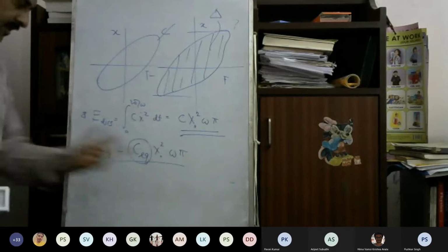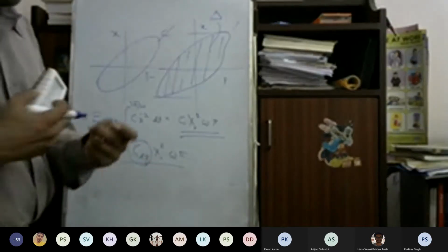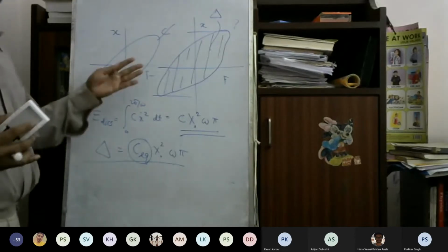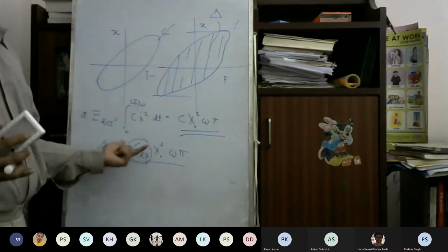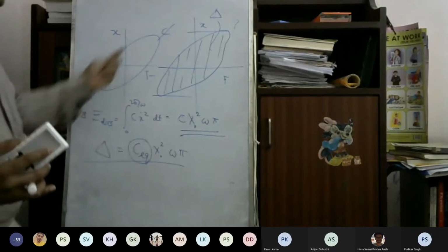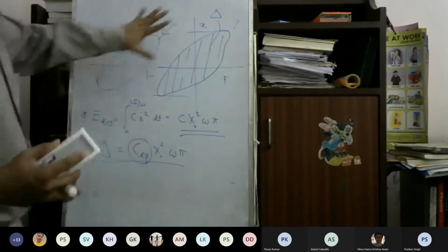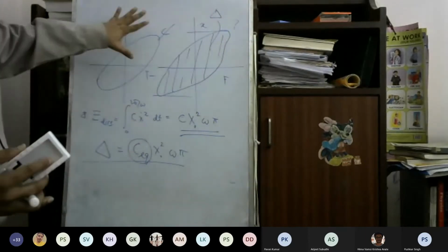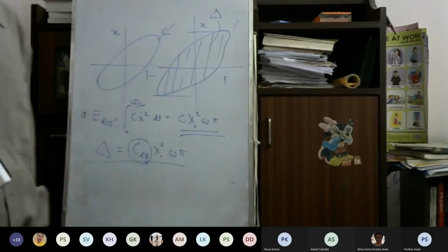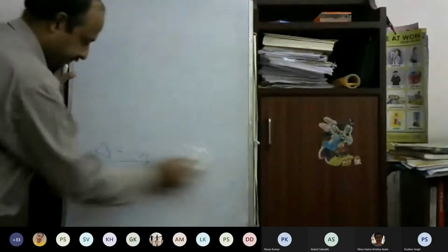So this is very important, because in many systems where we do not know the exact nature of the damping, we can approximate it as a linear damping, and take this coefficient as an equivalent value. So we consider an equivalent linear damping when the damping is not exactly linear. We just find out the equivalent viscous damping, which will give you the same energy dissipation. Is this clear? Yes, okay, sir. So equivalent damping gives the same energy dissipation.